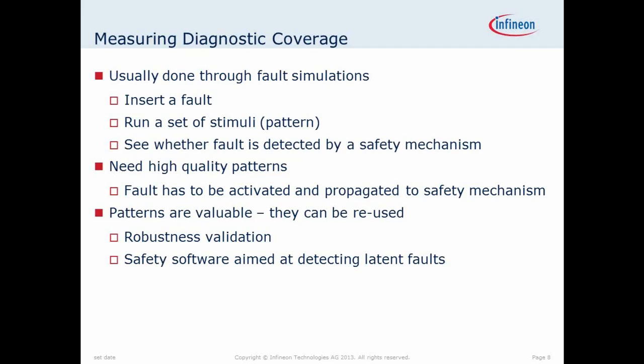This sounds okay, but in practice this can be difficult. You need very high quality patterns. So if you have a fault deep down in your design, you need a pattern which is going to activate that fault and then allow it to propagate to an output, or allow it to propagate to a safety mechanism.